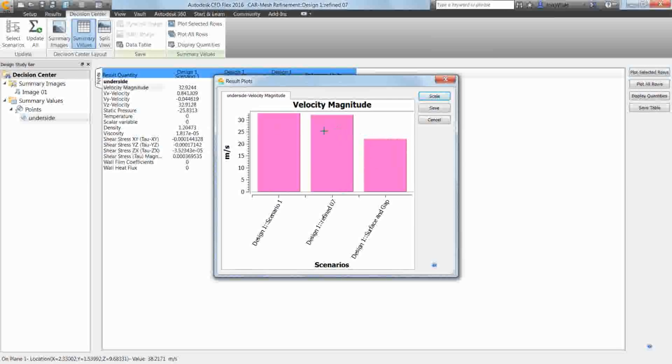And the important thing this raised for me, I guess, is that the first two results, even though there's 30% more mesh in the middle compared to the left, the results are really similar. And the reason for that is both meshes are bad. So this is why I would always say start with a good mesh. So use some intelligence, refine the mesh where you know you need it, and then adapt the mesh from there. And then you should be moving to some good results. Think that all makes sense, Todd?